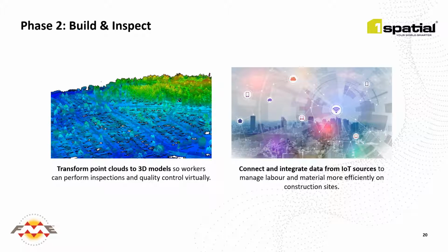During the construction phase, drones can also be used to provide an overview of the site to monitor progress and overall safety. The same construction firm that I mentioned earlier scheduled weekly flights from an independent contractor who supplied them with a full ortho photo of the site each week, along with LiDAR data. Both data sets were pre-processed by FME to make them ready to be consumed by their visualization software solution. And as a construction company continues, drone data can be used to create 3D models to verify what's been built at each stage, and it can then be checked against the design model.